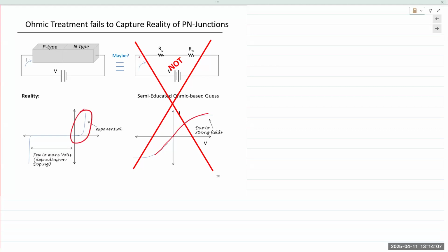As the voltage was increased, meaning it was turned more positive, there was no conduction, there was no current until a certain level was reached. Once that voltage level is breached, the current increases exponentially. So it's completely non-linear. Hence, we say these are non-linear devices, because the relationship between the voltage and the current is not linear. So far, so good, right?